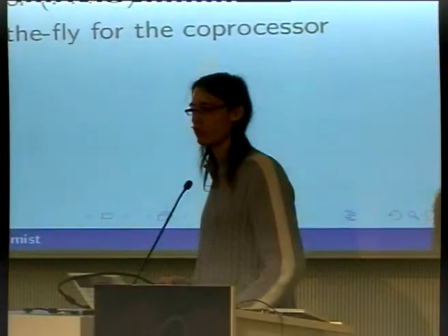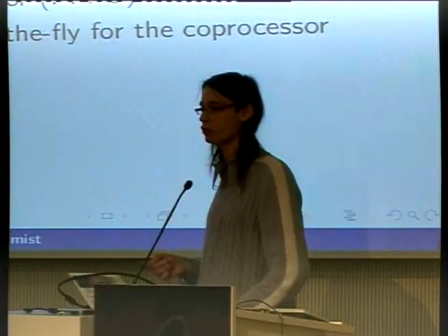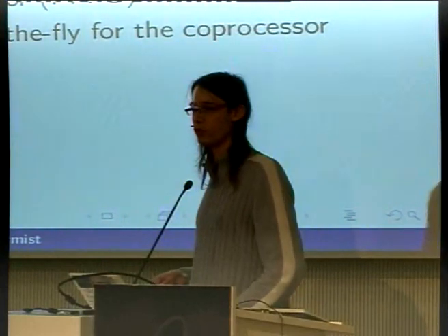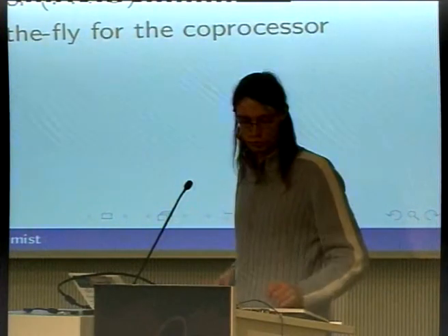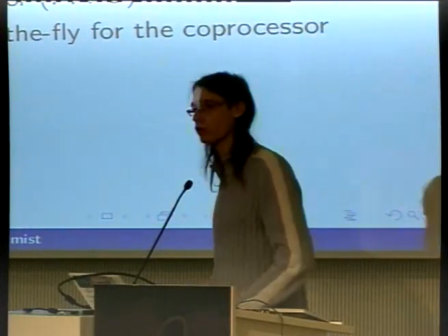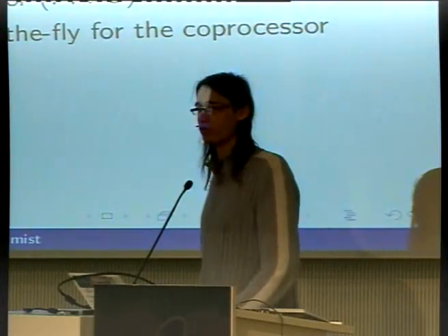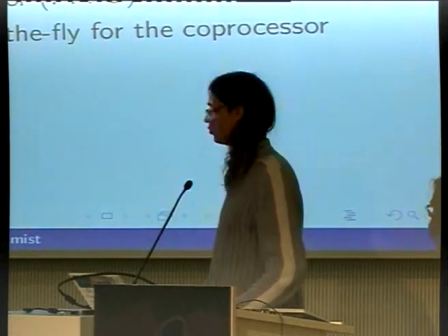On real cases, with an FPGA running at 100 megahertz, it does 75 billion floating point operations per second, and uses, on this FPGA, which is a Virtex-4 25, approximately 20% of the FPGA surface. So it's not too bad.